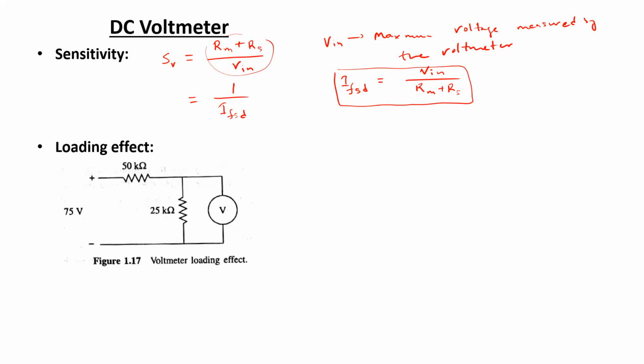So, to measure voltage drops across high resistances, let's say if a high resistance branch is available, in order to measure voltage using a voltmeter across that high resistance branch, a voltmeter with high sensitivity should be used. As the voltmeter sensitivity is normally defined in terms of ohms per volt, a high sensitivity voltmeter means that the resistance of the voltmeter arrangement should be high as well.